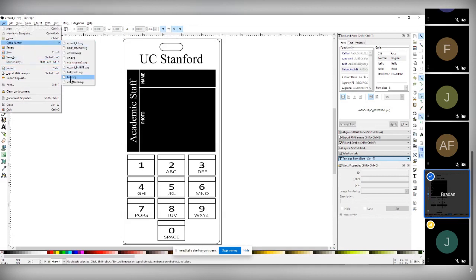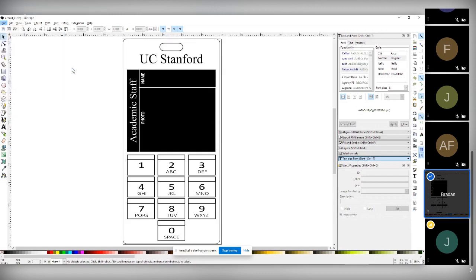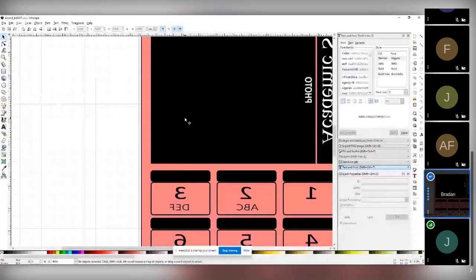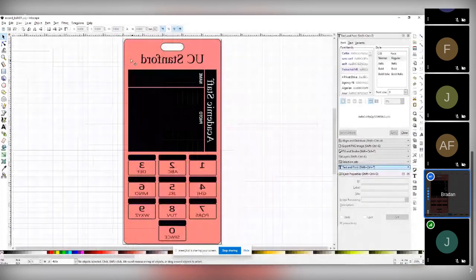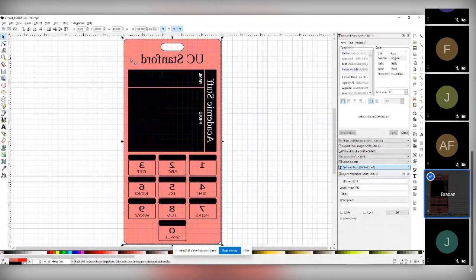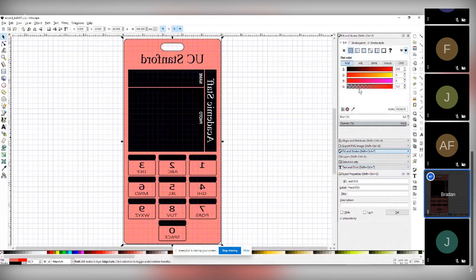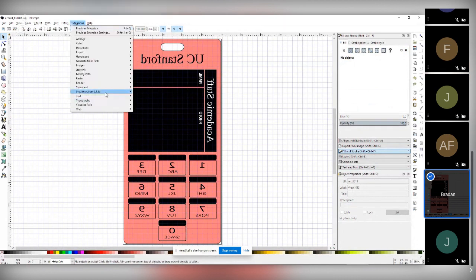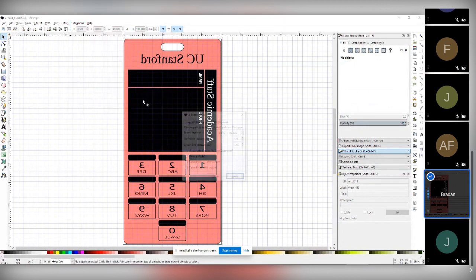Open recent, KiCad B Silk. So here it is. I've flipped it around. You'll notice that to make my life easier to see, because this is going to be a red board, I did a fill. And as I told you, if you set the transparency below 128, this fill will actually not be part of the footprint. So if I then went in and took this and generate my output,